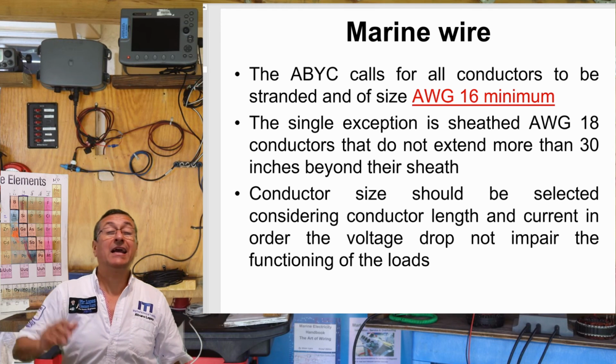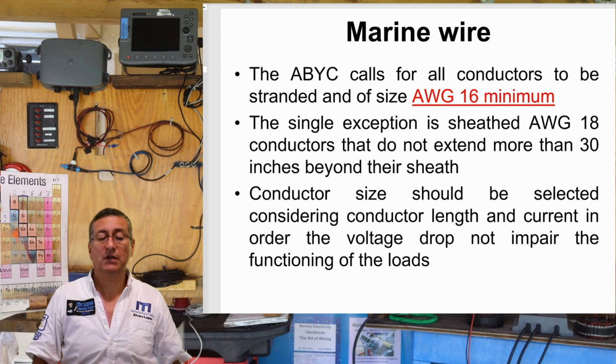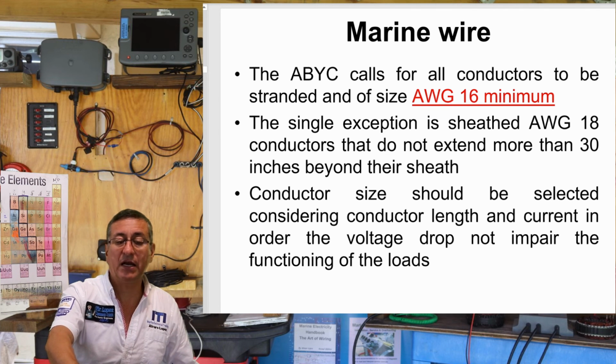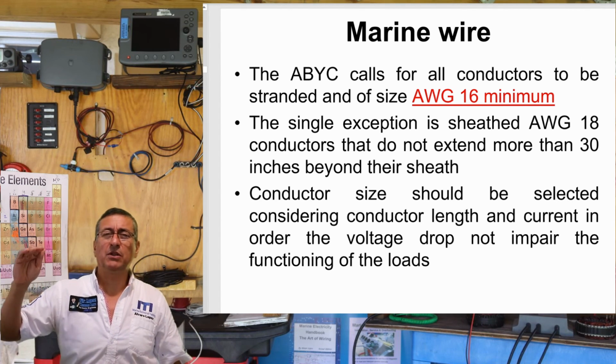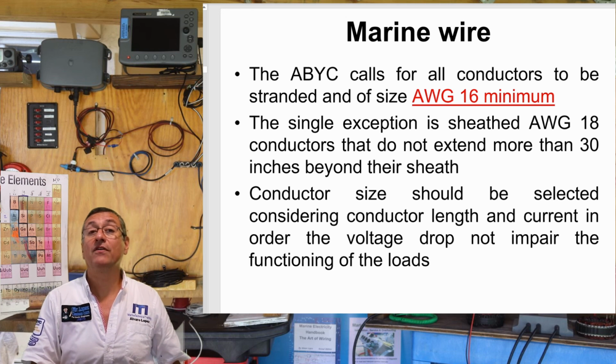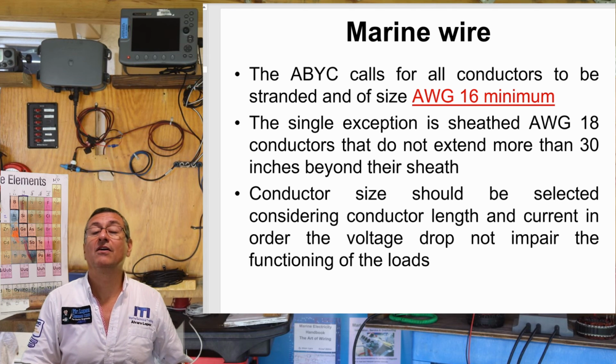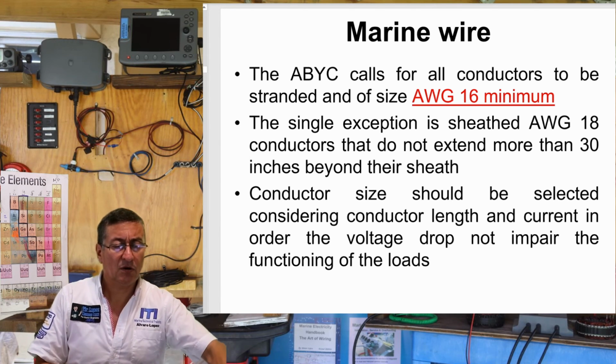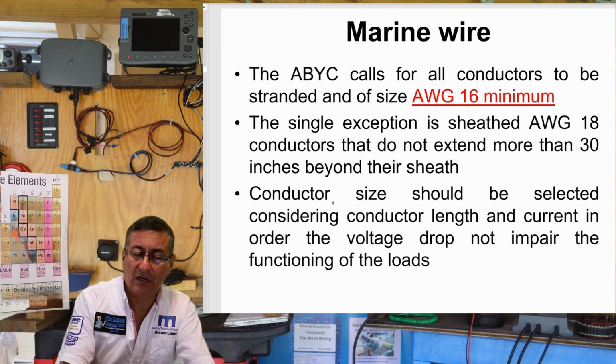All right. And the cranking cables, the battery cables, are bigger, with bigger numbers, between 6 and 1 zero, 2 zeros, 3 zeros, 4 zeros, depending on the intensity.